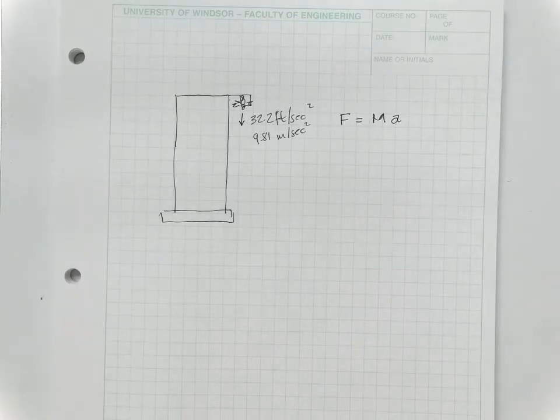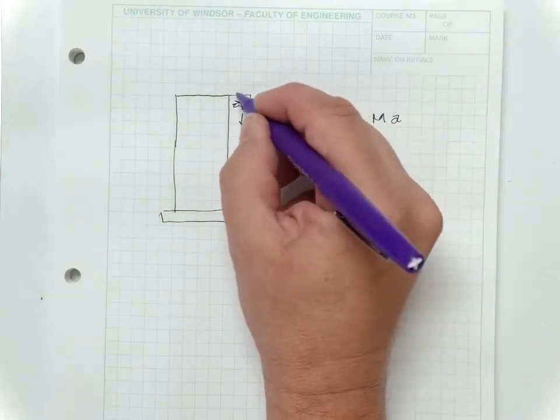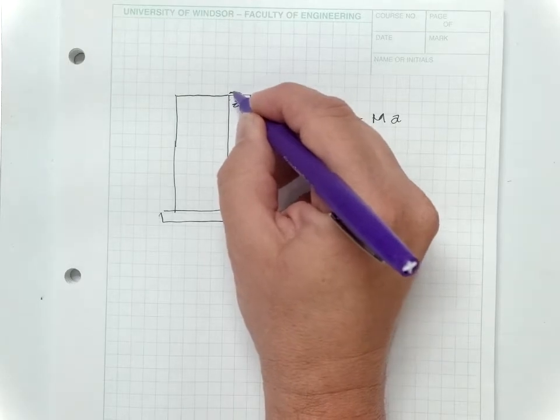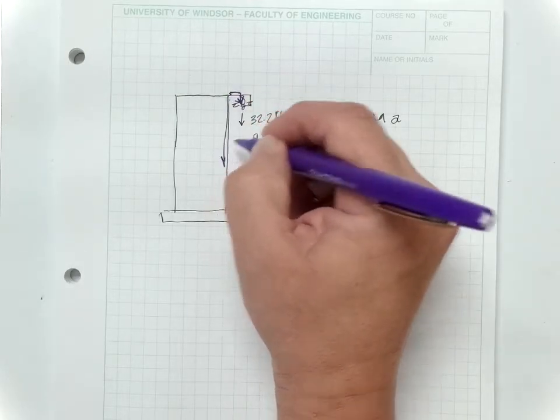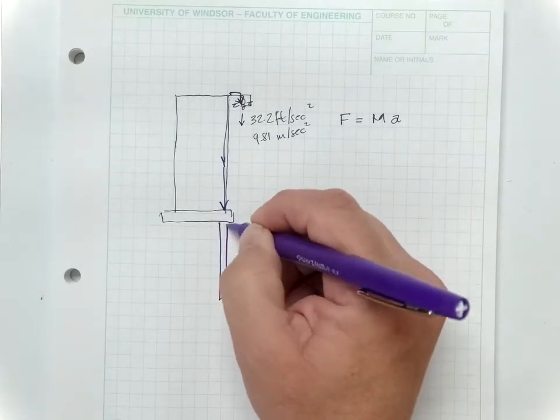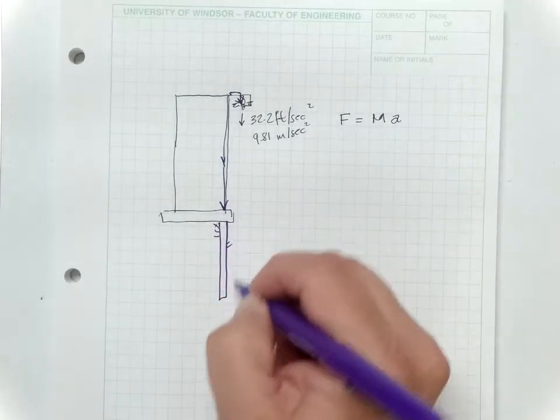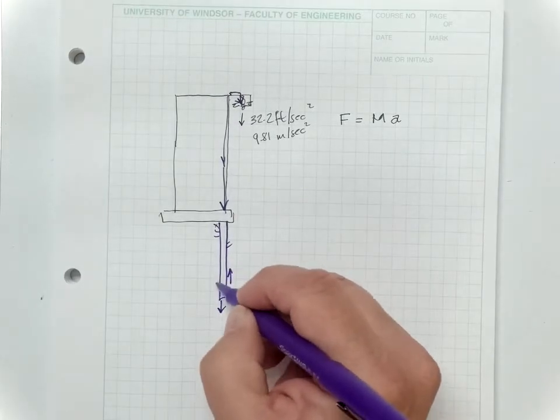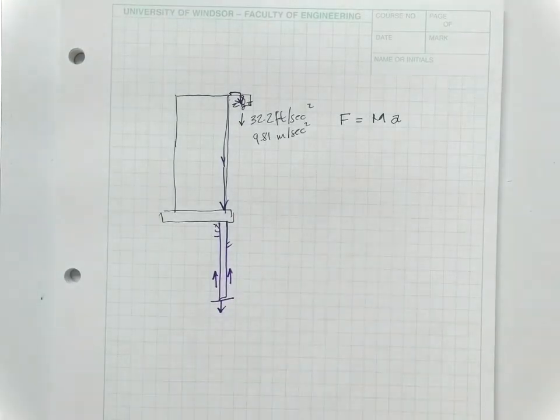And that load follows a path, which we refer to as, because we're engineers, what would we call the path that the load follows? The load path, right? We're not very creative people. So what we would see is the load of the bat goes down this way. It pulls on this, which pulls on all of these, pushes on all of these things, which pushes on the foundation, which probably, in our case, pushes on a pile, which pushes onto the soil.